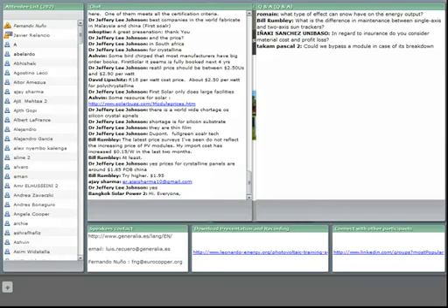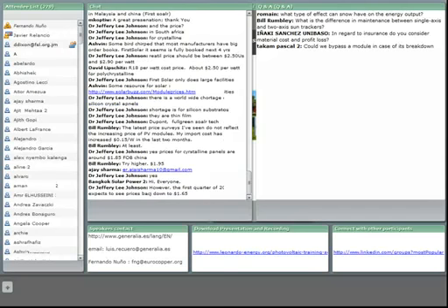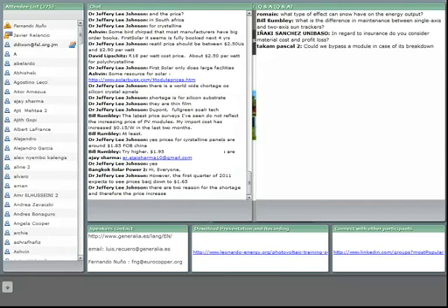So here we have another interesting question from a user who is asking if we can bypass a module in case of breakdown. Well, normally we cannot do this kind of solution because we might unbalance the array of modules. So we might get a different voltage from that array than the voltage that we have in the other arrays, as the modules are connected in series and parallel.